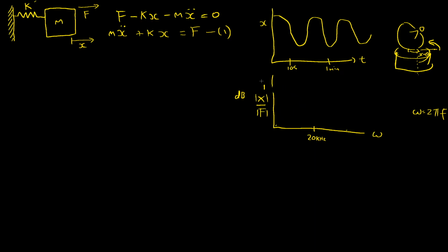Now there's a bunch of reasons we care about the frequency domain. One of the main ones is if you're designing a system, it's much better to hand someone a system and say, I can tell you exactly how your system will respond to any input you give it that's within this frequency range. Rather than saying, okay, I'm going to have to poke the system at given frequencies and capture a whole bunch of time domain plots in order to figure out how it will respond. And so this becomes a really useful tool.